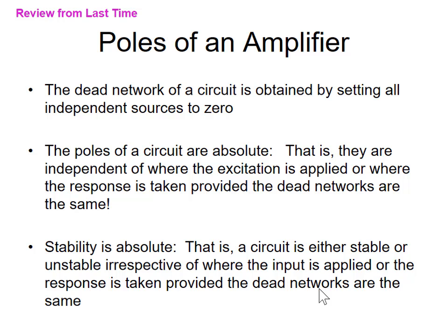So notice that if I want a different output, I just replace the excitation vector in a different column in this determinant. What have I done to the denominator? For different outputs. Stays the same. That denominator gives us the denominator of the transfer function.